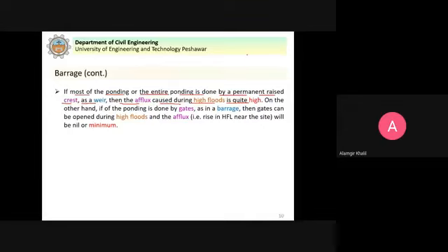As we already studied before, when we have this as the structure, let's say we have any weir, there will be a rise in the water level here. If you remember from hydraulics, the backwater curve. So this is efflux. Clear? This rising of the water level, this is known as efflux. In irrigation engineering, we call this efflux.